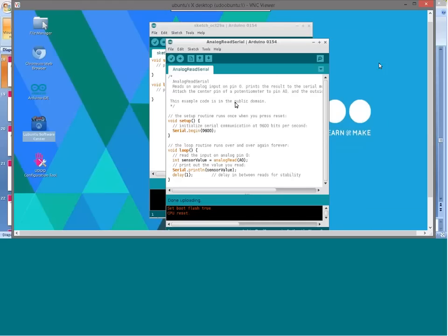And how do I access these values that are written by Arduino? I should do a simple edit here. So I have my serial port, which is running at 9600 baud. I can leave it like this. The really important thing, if I want to read from Linux, is to use Serial.write instead of println.